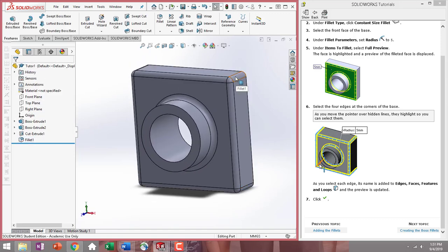So these outside fillets are nice. They will add material while our inside fillet cuts away the material. Fillets are really handy because when you're building parts with 90-degree corners, if there's no fillet there on the inner corner, like extra material, then your part can easily break. So the fillet provides more material so that part's more sturdy.